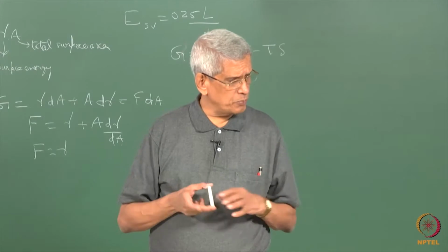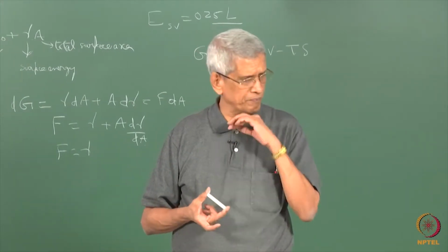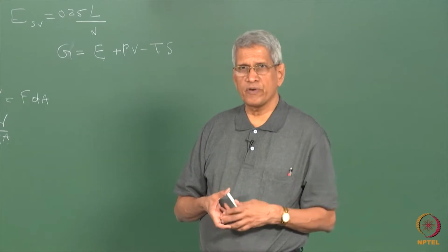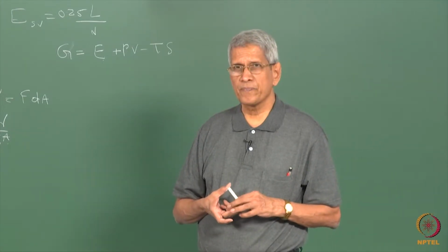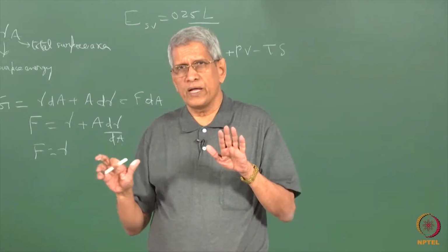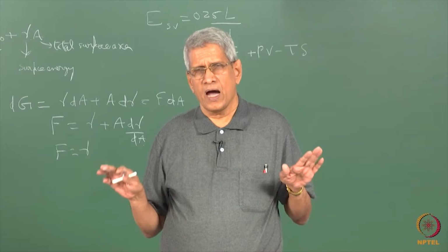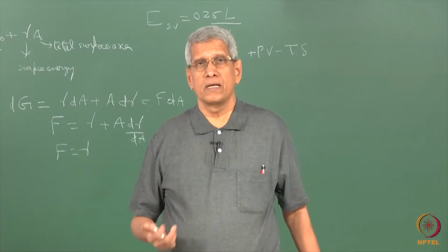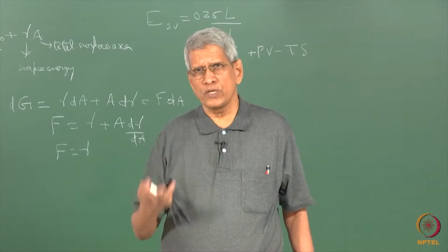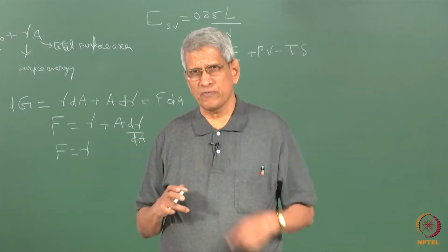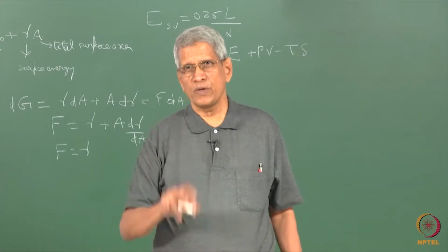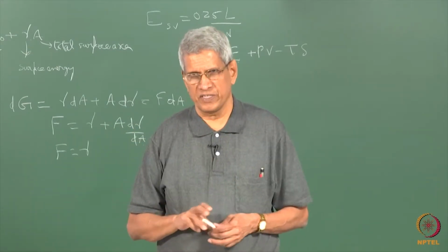Here in this table, what is being given is the surface energy which has been calculated close to melting point for different types of samples. And in the cases which we have considered so far, we have looked at close packed planes or low index planes. And when we look at surfaces, there are two things which we have to consider: one, the energy of the surface, and another, the structure of the surface. The structure part of it we will come to later, but now we are essentially trying to concentrate on the energy of the surface.